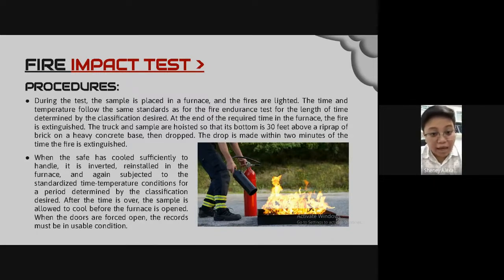When the safe has cooled sufficiently to handle, it is inverted, reinstalled in the furnace, and then again subjected to the standardized time temperature conditions for a period determined by the classification desired. After the time is over, the sample is allowed to cool before the furnace is opened. When the doors are forced open, the records must be in a usable condition.